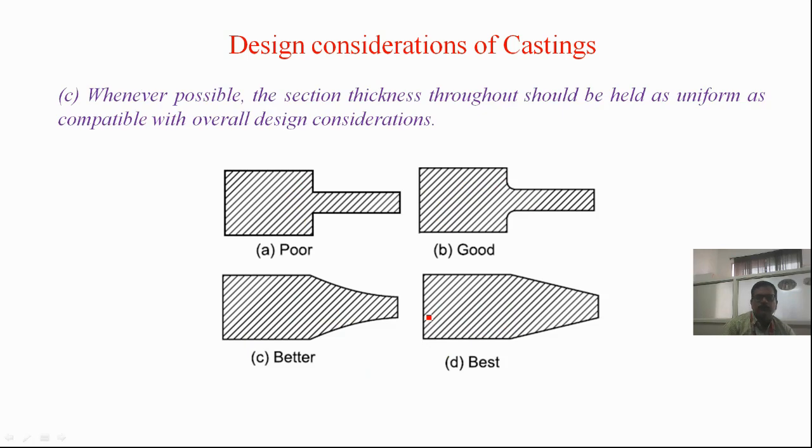So here you can see again the sharp edges and the section is long. You can see this section is long and this is thin and there are sharp edges. So having such long sections with sharp edges is very disastrous when casting.